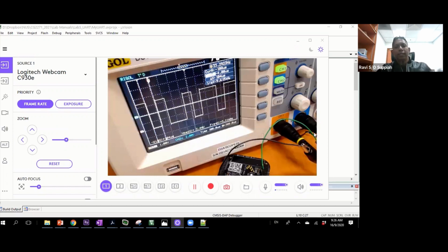All right, so that is the indicator of the start bit. So the receiver also knows that suddenly somebody pulled the line low means somebody is going to start transmitting data. Correct. So the moment one of the devices pulls the line low, that informs the receiver that it's time to prepare and sample data in. Correct. So this is the start bit.